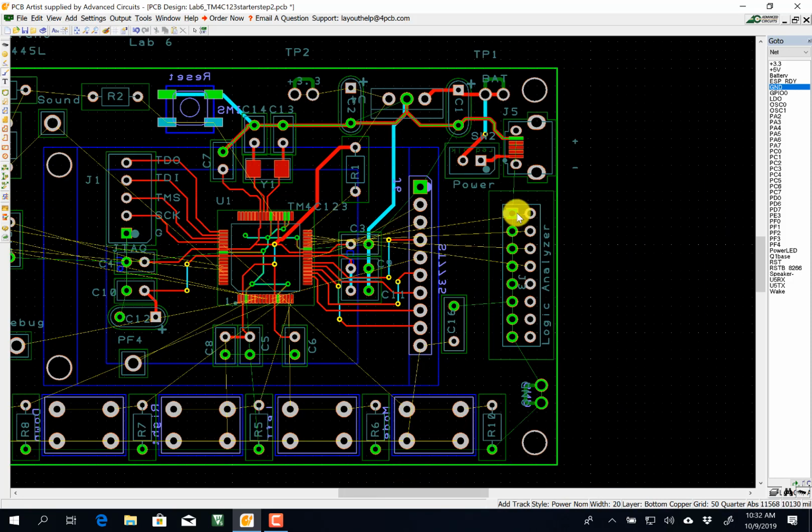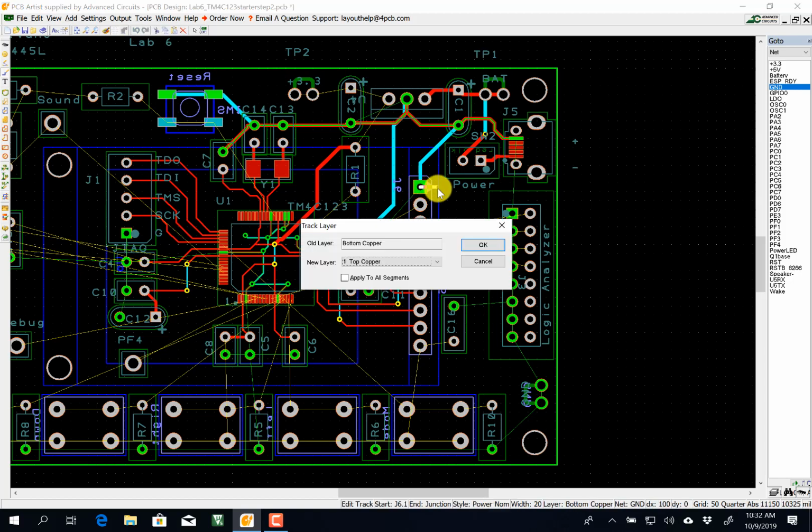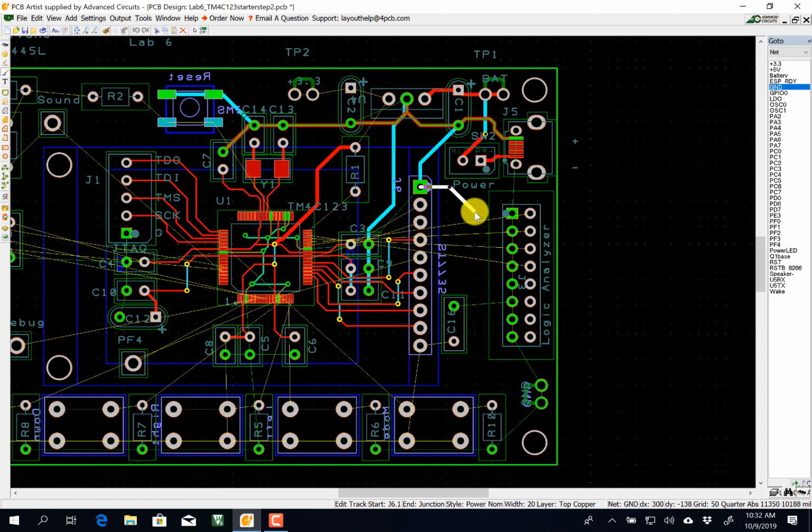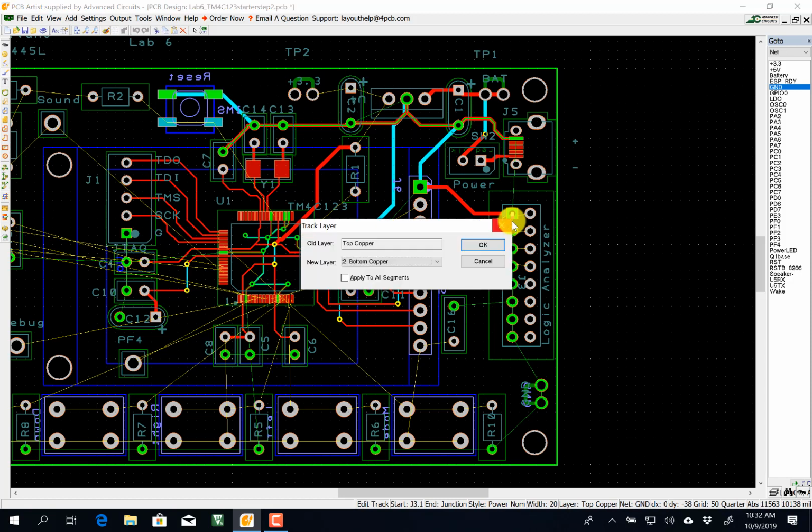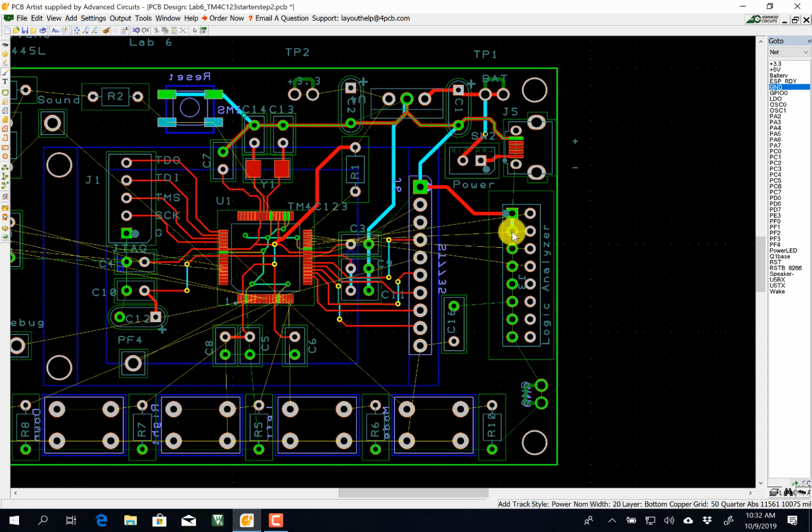All right. So now we got to get over there. Oh, here's a ground. I need to connect that one. So let's go here. All right. Yeah, that'll be easy. Connect the ground there. And now I can connect this guy to that guy. Let's put it on the top layer, because it's pretty much going right to left. All right, and let's put all these on the bottom layer. Click, click, click, click. Okay, so you see I'm using big traces here for my power and ground, as big as I can make it.